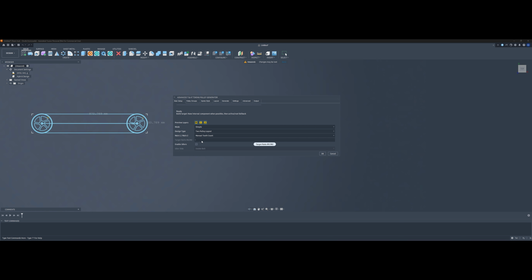In two pulley layout mode, we also have idlers. In this case, the idlers are mainly used for tensioning and layout planning. They can be placed on the inside of the belt or on the outside of the belt. When idlers are enabled, the solver places them in the open space between the pulley bodies. This keeps the idlers visually centered between the two main pulleys, even when the pulleys are different sizes.